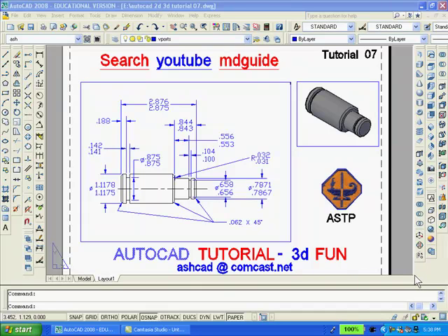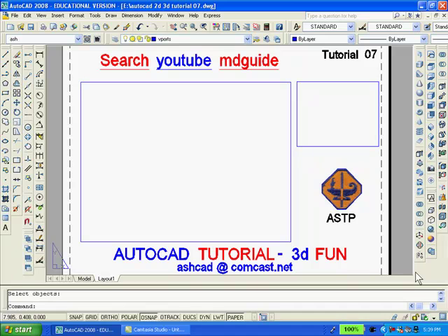What you are looking at is my 2D drawing and solid model of the object in paper space. The first thing to do is to erase both the large and small viewports. You can see that the drawings disappear from paper space. All that remains are two rectangles which I drew previously to serve as templates for when I redraw the viewports later on. To get into model space, I'll click the model button.